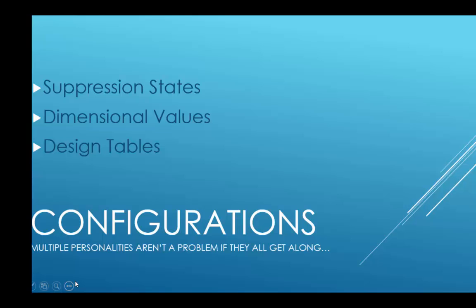In fact, if you ever get really bored, under the ANSI standard there are about 11,000 socket head cap screw variations available out there. And why would you deal with 11,000 variations of files? Do I want to manage 11,000 files, or would I prefer just to manage 1 file? With configurations, you're able to do that, okay? That's a little extreme. Please do not handle 11,000 configurations in a file.